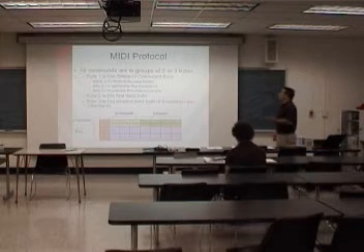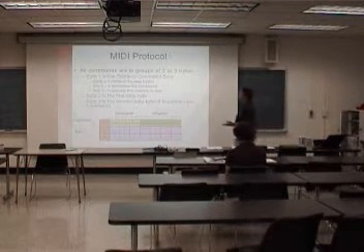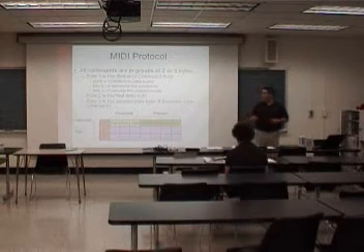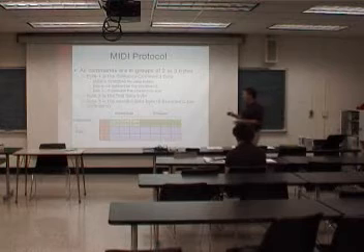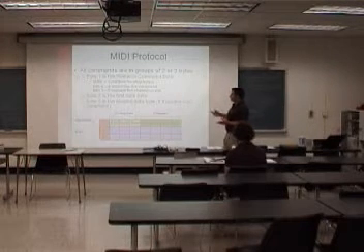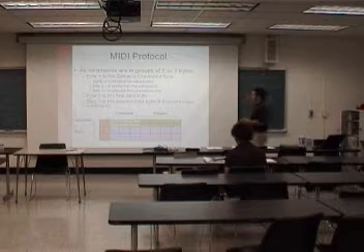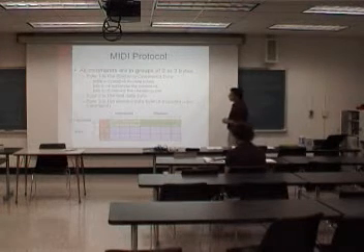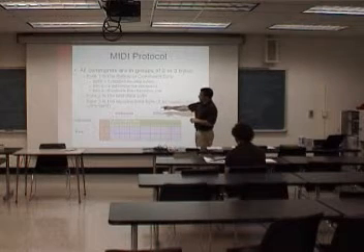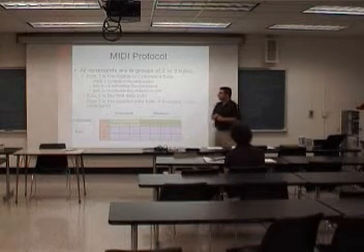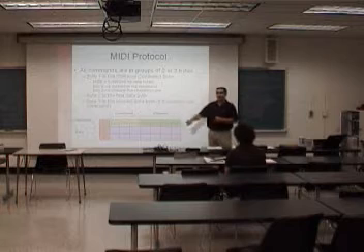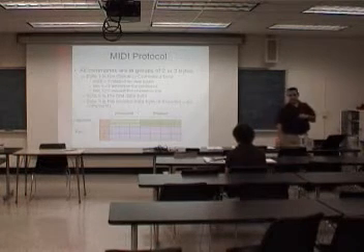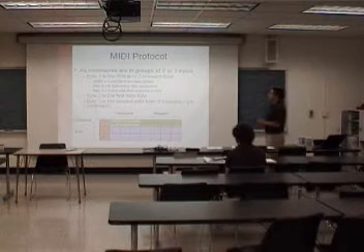Okay, so MIDI protocol. Again, very simple. All commands are in groups of either 2 or 3 bytes. So byte 1 is either called the status byte or a command byte. I think status is more common, but I've used command for the most part here. Very simple. In a command byte, the most significant bit is 1. In all data bytes, the most significant bit is 0. So you immediately know whether something's a command or a data byte, just by looking at that bit.